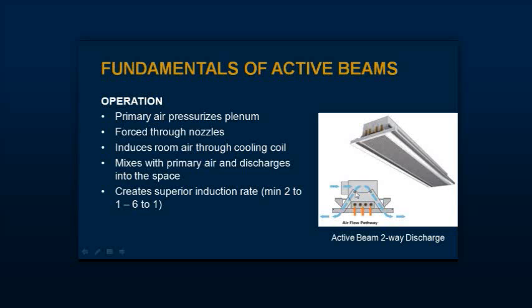In terms of flexibility for radiant systems, one of the bigger challenges to me is that when we're cooling with them, or heating for that matter, even though we could put in really cold water or really hot water to drive the energy exchange between these radiant panels and the occupancy, we can't really go beyond a certain level of differential, because the occupant, if it's hot water, would have a hot head, and they would call and complain about having a hot head. People are very sensitive at the head level, so we have a difference in temperature that we can't exceed before we start getting thermal complaints.